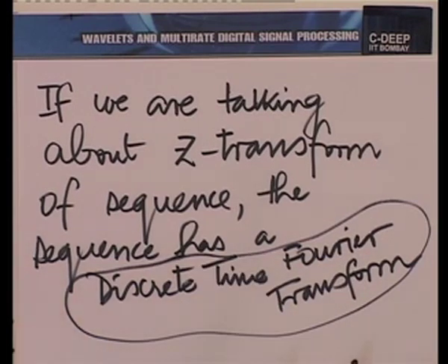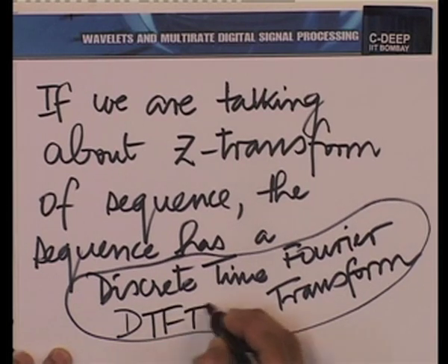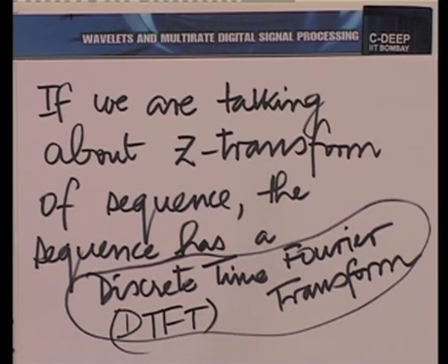This is an important concept. Either way, in case the unit circle is included in the region of convergence, then we have an even more interesting interpretation of the system function or the sequence in question. In fact, all these Z transforms encountered in the Haar filter bank satisfy this.